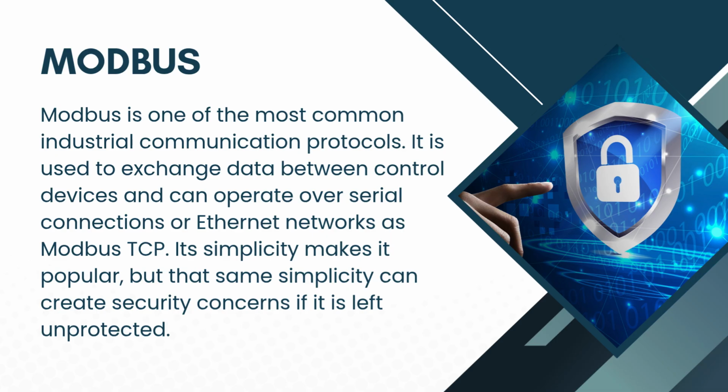Another common protocol you should know is Modbus. Modbus is one of the most common industrial communication protocols. It is used to exchange data between control devices and can operate over serial connections or Ethernet networks as Modbus TCP. Its simplicity has made it very popular in industrial systems. At the same time, that simplicity can create security concerns if it is left unprotected. This is an important reminder that convenience and compatibility do not automatically mean security.